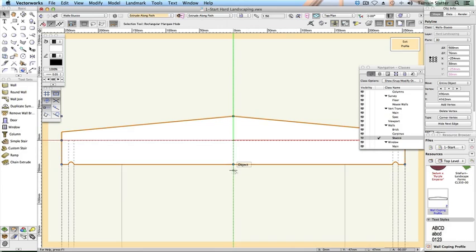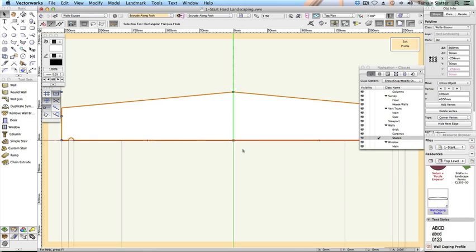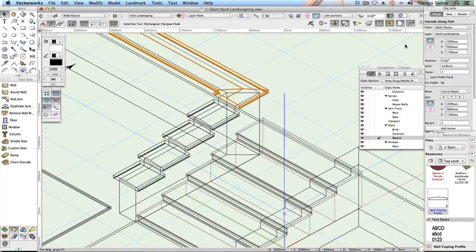This is the part of the profile that is currently aligned with our original path polyline. Click on the bottom centre of the profile shape and drag it up to snap onto the origin 0, 0. Click the orange Exit Profile button at the top right of the screen. The coping is now positioned correctly on the wall.